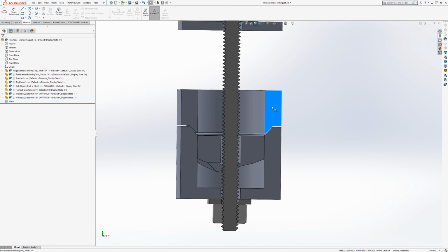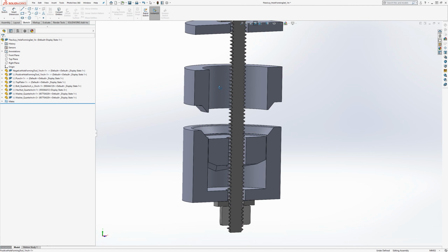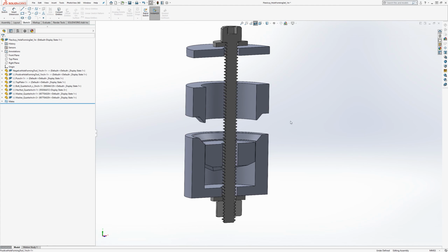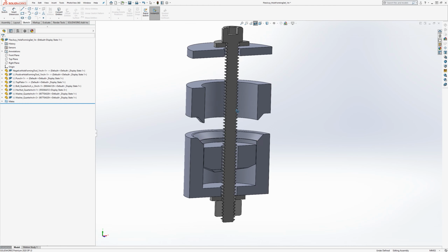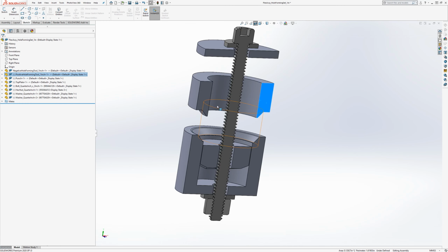So we can see each of the parts here in this assembly has this dash and arrow here, and that means that there's external references to that part. And so these parts are each referring to something to take their shape. In this case, it's not actually in this assembly, because in top-down design, you can't really have parts be unconstrained like this flexible assembly here. So in this case, this assembly is just for demonstration.